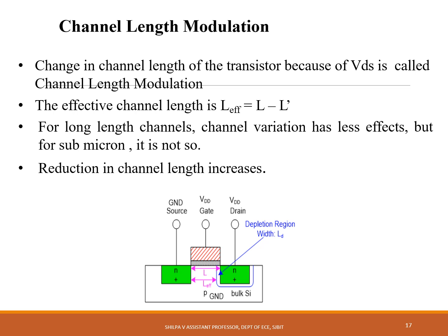The next non-ideal effect is channel length modulation. Ideally, IDS is independent of VDS for a transistor in saturation, making the transistor a perfect current source. But the PN junction between drain and body forms a depletion region with a width that increases with VDB, as you can see in the diagram.